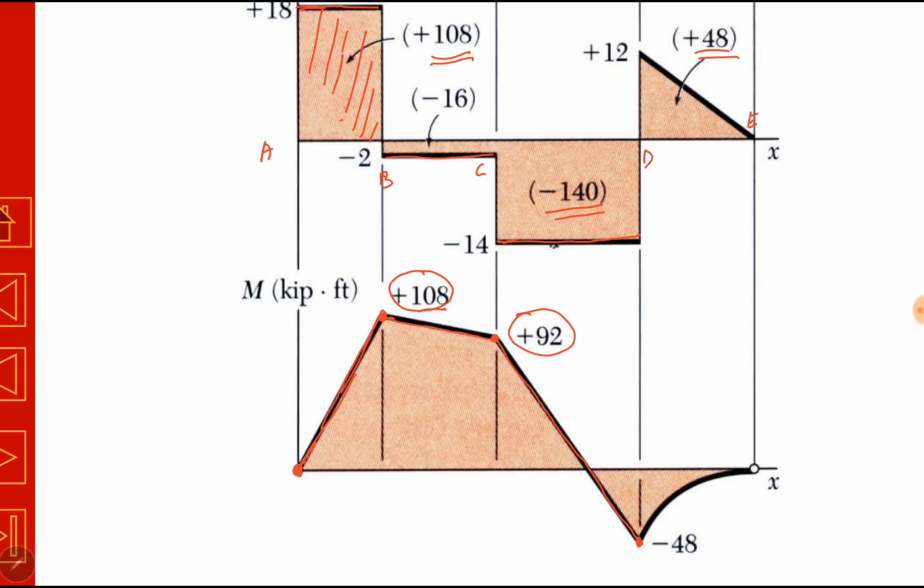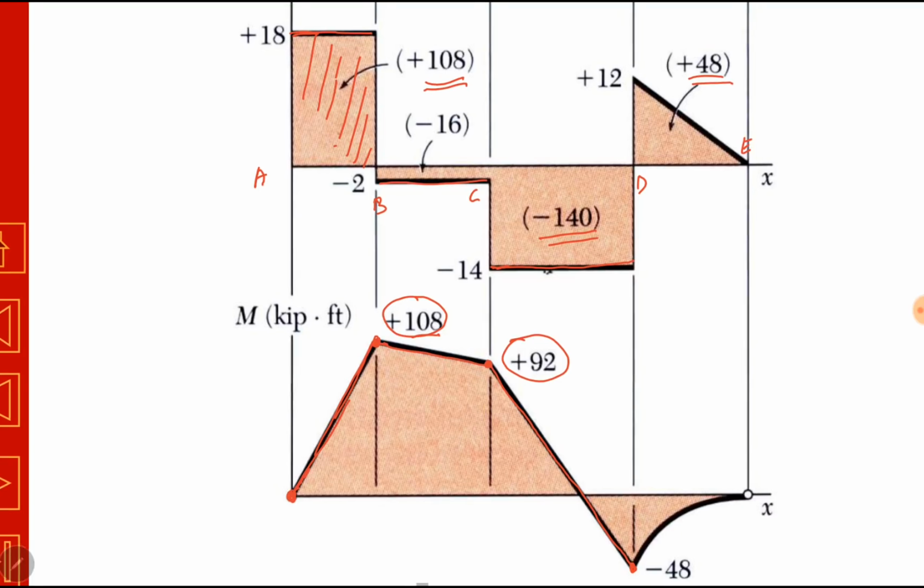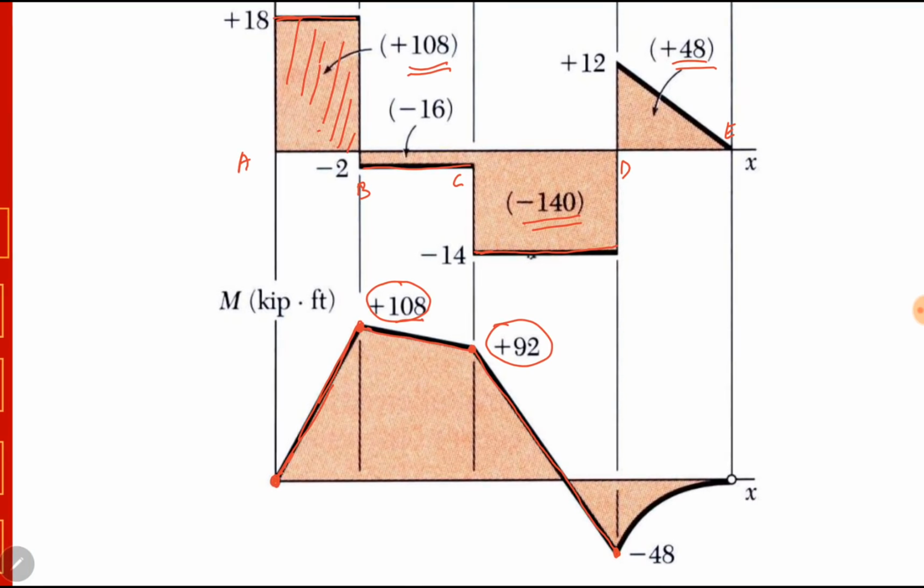Okay. So this is how to draw shear force and bending moment diagrams using the relationship between load, shear force, and bending moment. We simply need to know the area under the shear force curve and the load curve. Here also we can do it mathematically: MB minus MA is the integral of V dx between XA and XB. Now MA is known to us, it is 0.